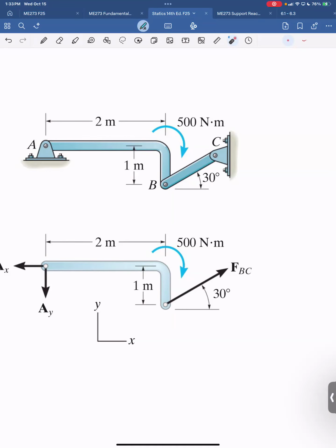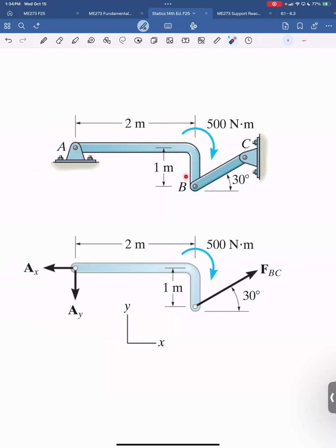And then the next step is, of course, coordinate system. But when you're drawing your free body diagram, when you cross this pin C, you might think, oh, I got to put two unknowns there because it's a pin, but I already got two, so I must have made a mistake. Let's, did this earlier. So in this case, you were drawing, you came across this support A, so you put in the two support reactions. Doesn't matter which direction you put them. I always put them positive, but it doesn't really matter. And then you keep going around.